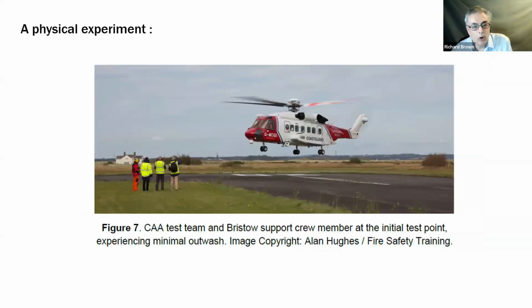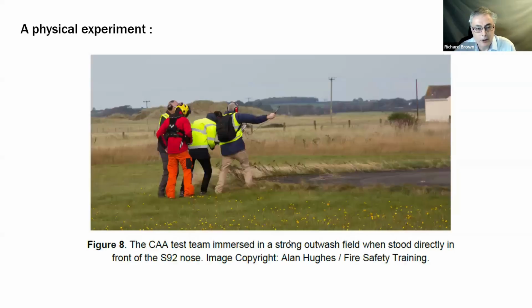Now, what the CAA decided to do is to actually test that contention in the physical environment, based on the unsteadiness that we'd revealed in the simulations of eVTOL aircraft. So here you see the CAA test, with Mike Price standing with his anemometer, measuring the outwash in the flow below a hovering S-92 helicopter. And you can see here that the outwash looks particularly benign. Until you change your position with respect to the helicopter, then all of a sudden you find yourself buffeted from all sides by a very strong outwash field generated by that particular helicopter.